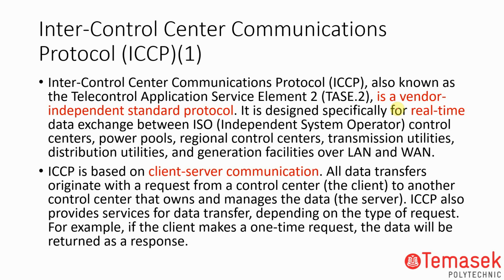ICCP. It is a vendor independent standard protocol, also known as Telecontrol Application Service Element 2, TASE.2, or ICCP. It's designed for real-time traffic, and can be used for LAN and WAN. It is client-server communication, it allows managing of data, and it provides data transfer depending on the request. For example, a client can make a one-time request.